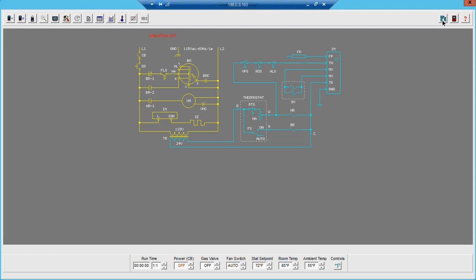We have a gas valve, we have a flame sensor, we have an ignition module, we have a thermostat, and obviously we have our blower motor, vent motor, and our igniter. So the customer is complaining that the burners fire but then immediately shut right off. So that should be a very big clue to what is wrong with this particular piece of equipment.